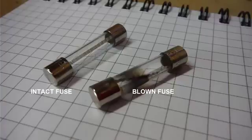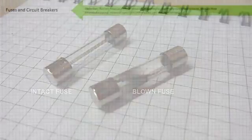If the switch is closed, current will flow. If the switch is open, current will not flow. Fuses differ from traditional switches, though, in that fuses are one-time use only. When a fuse blows, it is rendered inoperable, and here's the important part. Once the fault that caused the blown fuse has been identified and rectified, the damaged fuse must be replaced with a functional fuse with the correct rating.